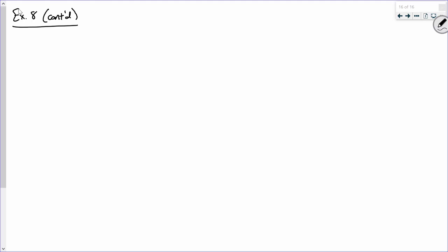All right. Okay. So here's how we'll do this. I'm going to calculate a nominal capacity of an edge bolt, and I'm going to say it's 1.2 t Fu times the minimum of Lce or 2 bolt diameters. But I don't need to do that evaluation at the end because I've already done that. It's going to be Lce. So let's plug and chug. You tell me, it's 1.2 times, now what's the thickness? 3/4. Again, we're looking at the center plate, so 3/4. All right, Fu, what was that? We looked that up way back. 58.